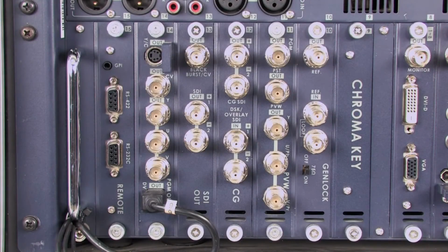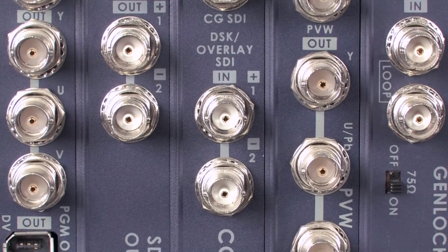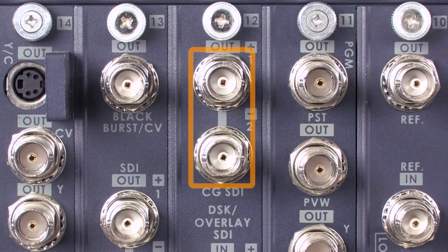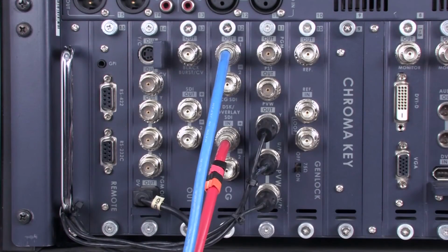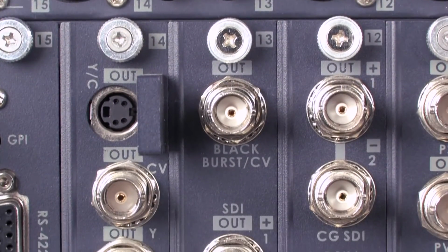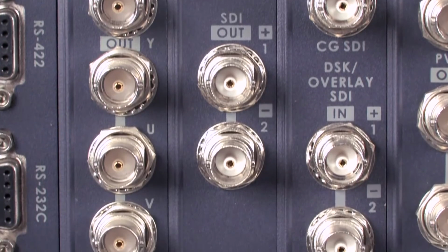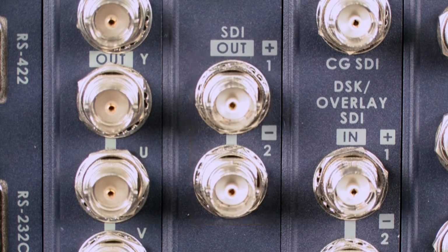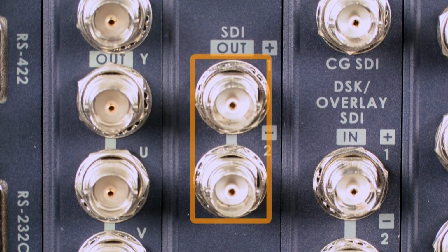Card slot 12 is for the SDI CG Overlay Card. The main function is to add support for SDI graphic or text character overlay. The card provides 2 groups of SDI input and 2 groups of SDI output for SDI loop. It is used to add a CG generator. One point to note is the SDI output on the card does not have the overlay signals cleanup output for the convenience of use with the on-site live recording of 2 types of signals, one with overlay and one without.